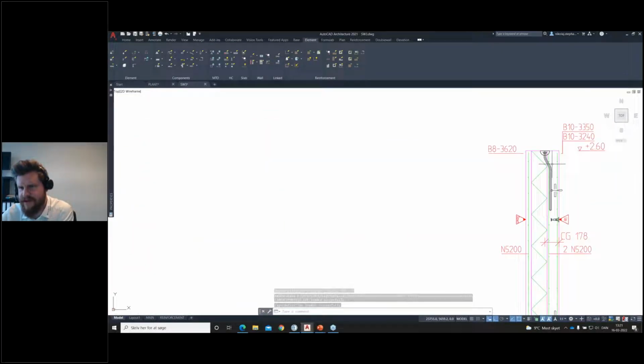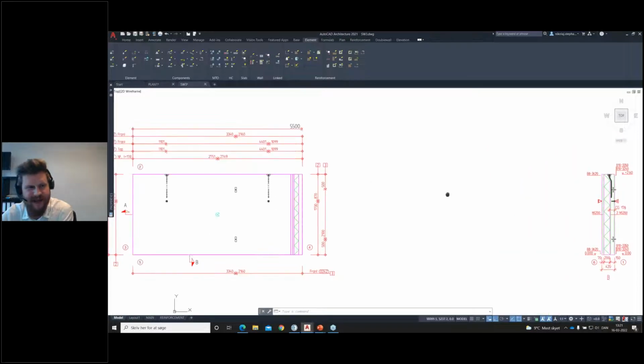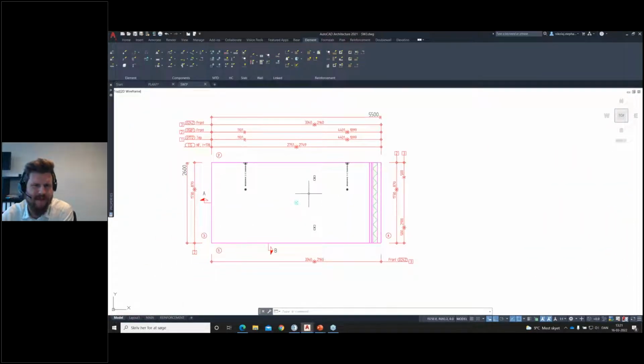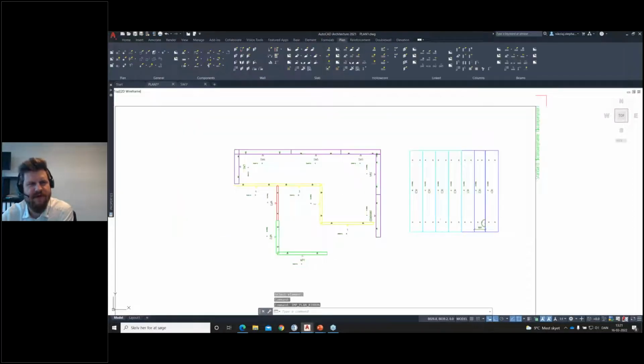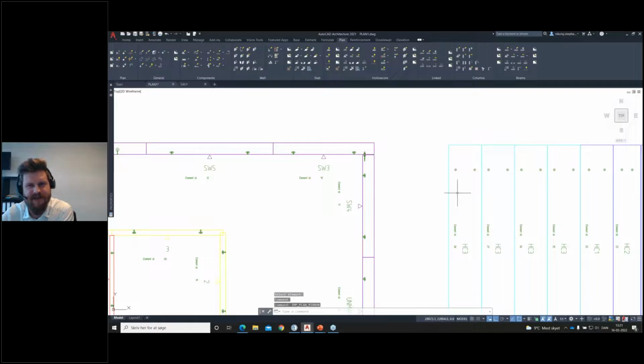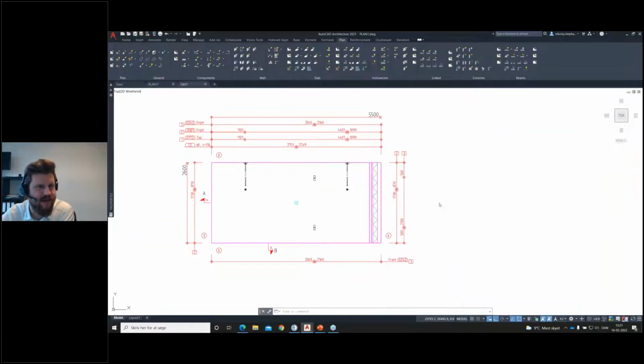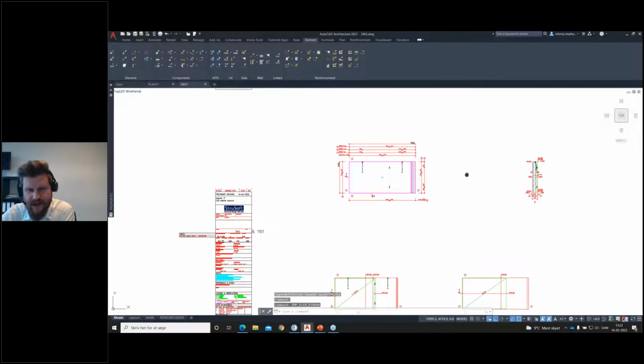We can see the lifter is now placed in the center of gravity like usual. This is one that goes into the concrete here. I haven't configured the automatic wall thickenings and so on. It doesn't move the wire loops. Why doesn't it move the wire loops? Because, well, we still have another wall connecting to it here. There's some different things in the solution and so on. So it does exactly what it's supposed to do everywhere here.